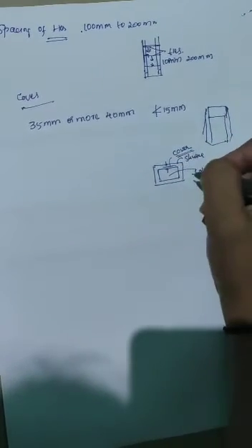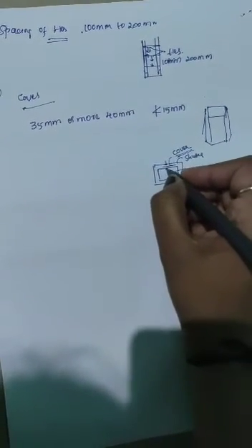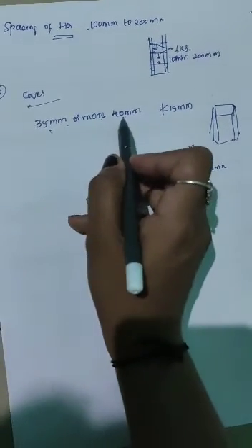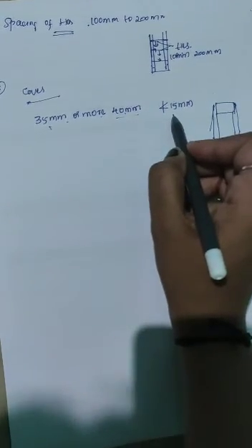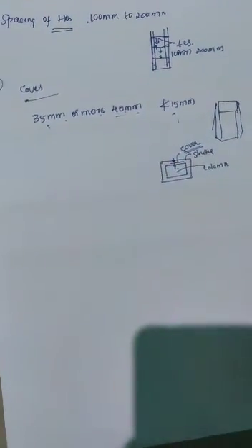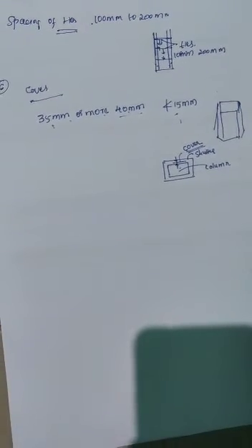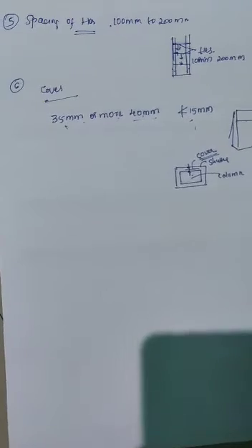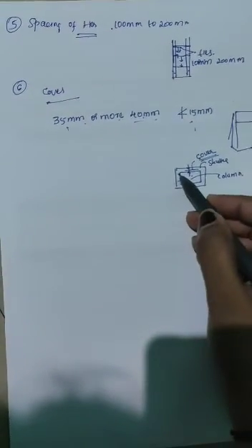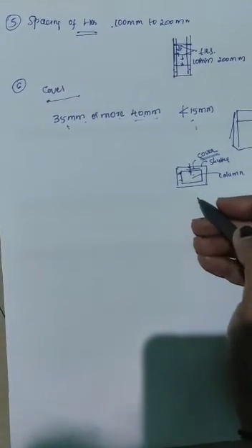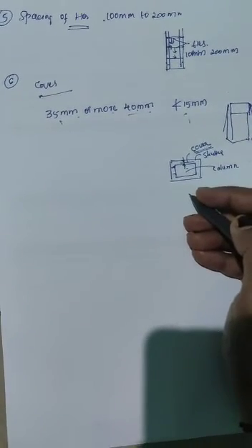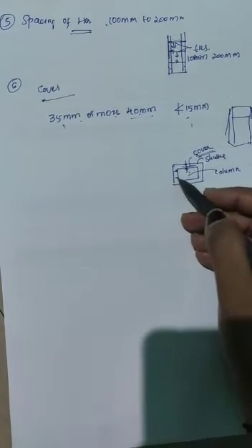So why is this cover provided? In between the shuttering and the concrete, there is a gap which is called cover. We can provide it as 35 mm or more, 40 mm, but it should not be less than 15 mm. The reason for providing this cover is, whenever we start the concreting process, if we are not providing this gap from the shuttering and the reinforcement, it becomes difficult for us to cast also. So that is the reason we are providing clear cover here.